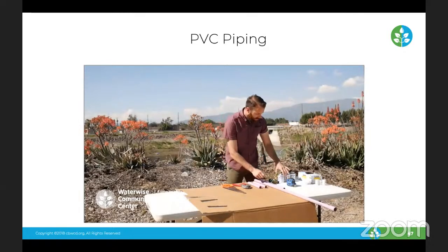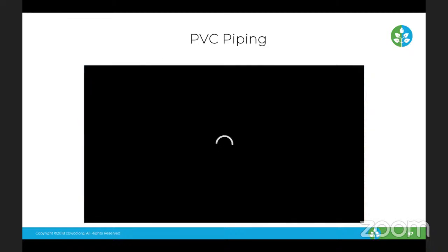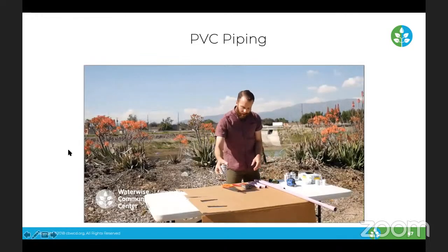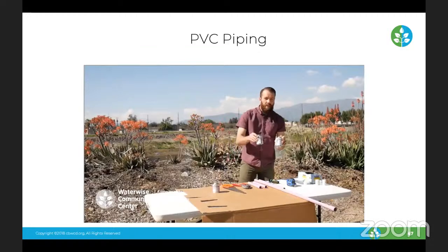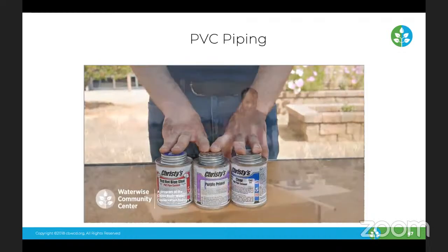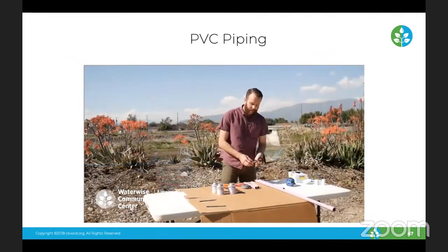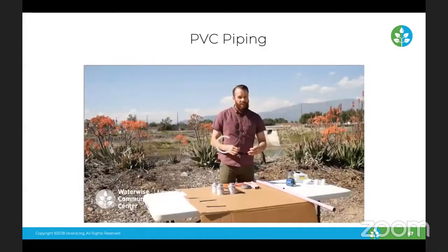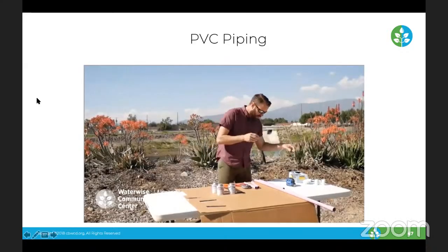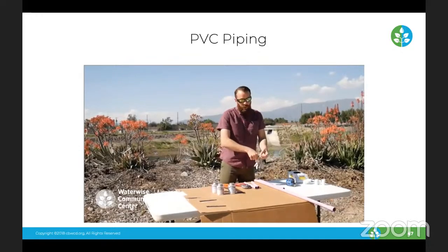And in particular, when dealing with PVC pipe, we need to use a PVC primer. I have 2 separate types of glues here. This one is blue glue and this is clear glue. Both do the same thing. The most important of all is your personal protective equipment. So you need a pair of safety goggles. And since we're using a solvent, you want to wear some sort of leather or rubber glove.